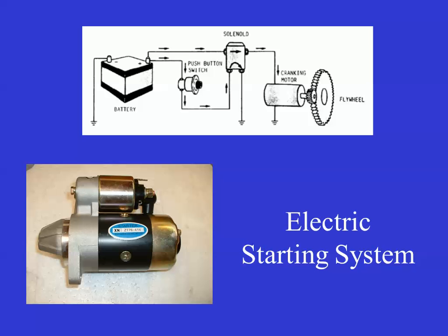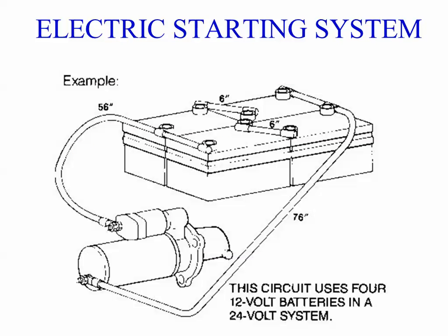So again, it's not voltage related so much as current related. The solenoid uses a small current to activate a solenoid which pulls in main contacts that handle the heavy current. If you had put a push button in the main start system, that heavy current through that button would burn up the switch fairly quickly.